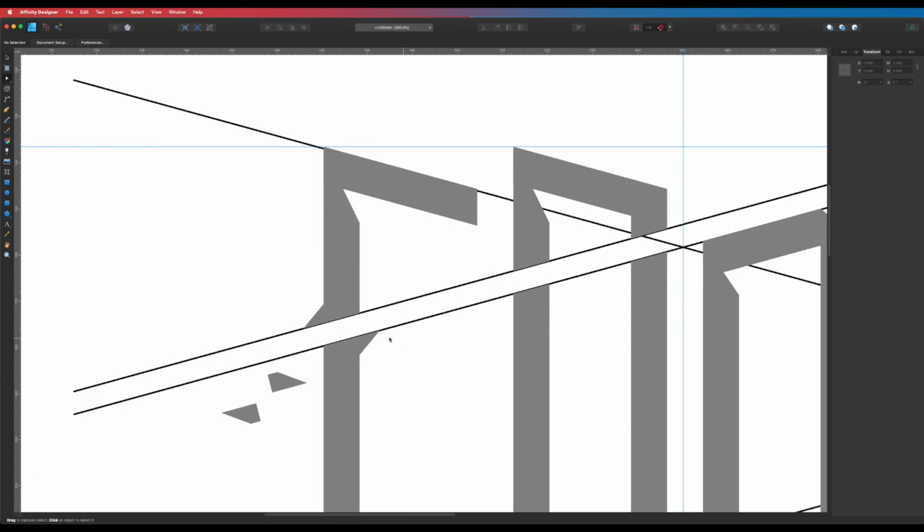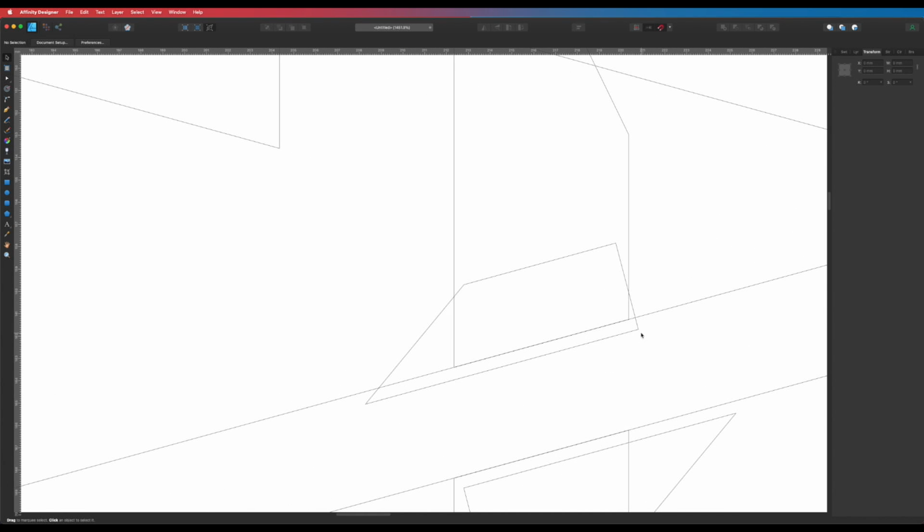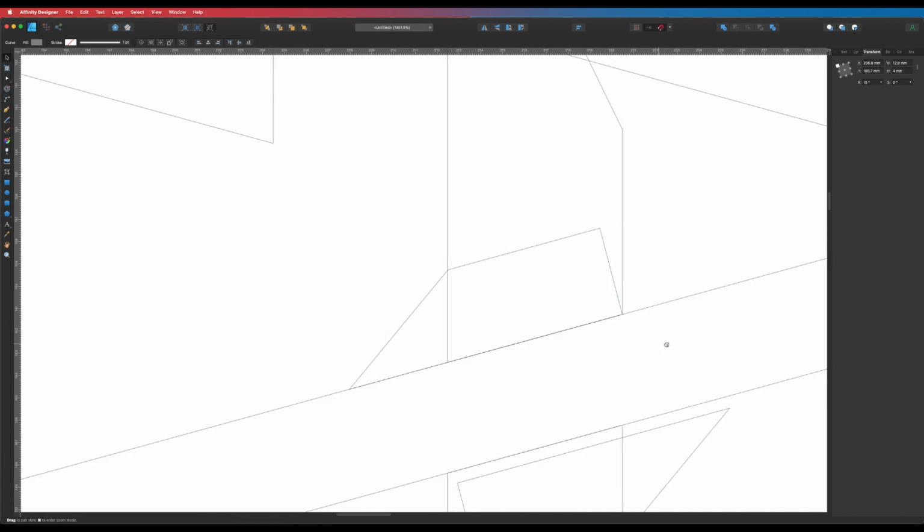Okay. I'm going to click and drag both these again. Hold down Alt, going to do a set here, and I'm going to do a set over here. And let's just get them all nicely aligned. So go to your wireframe, Command Y, get that little node over there, and just try to snap it to there. Perfect.